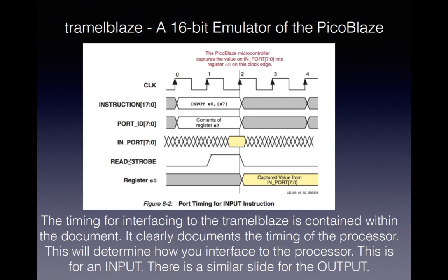So in summary, it's a 2 clock operation. On an input, during the first 2 clocks, the port ID has the address that we're trying to read. It's expected then that you respond, once you see the read signal, with the data that the processor is asking for.